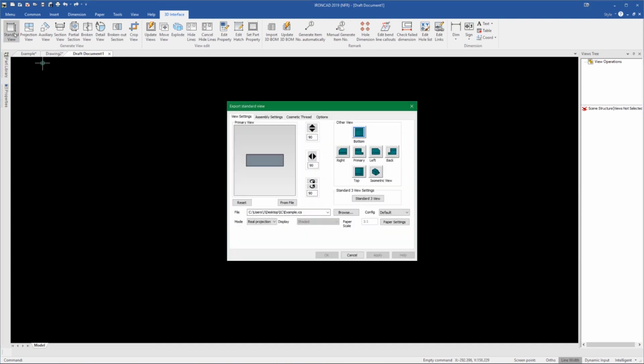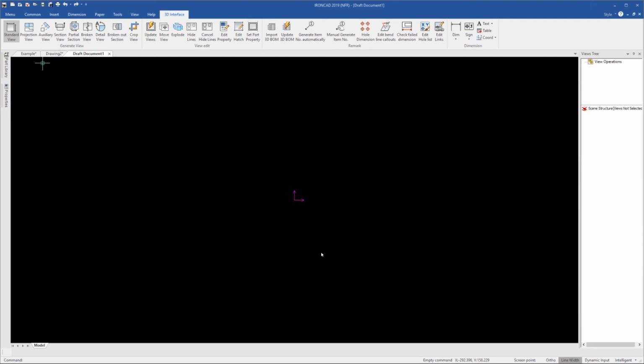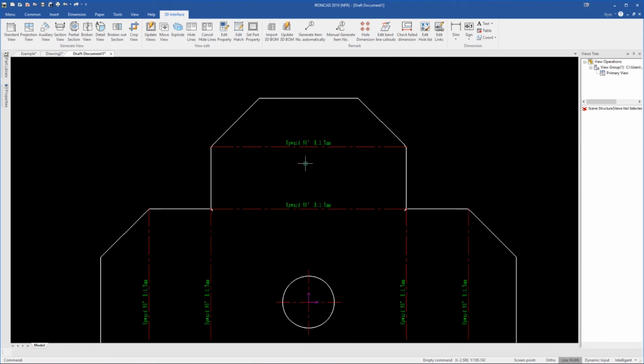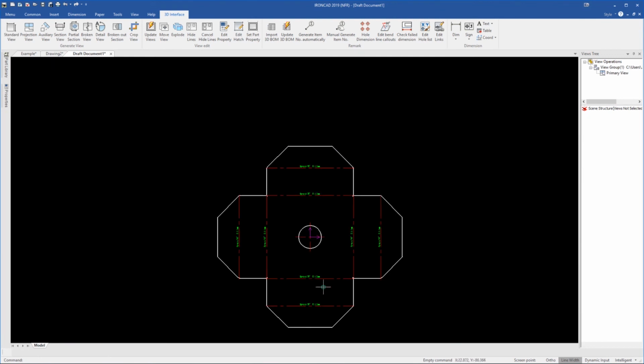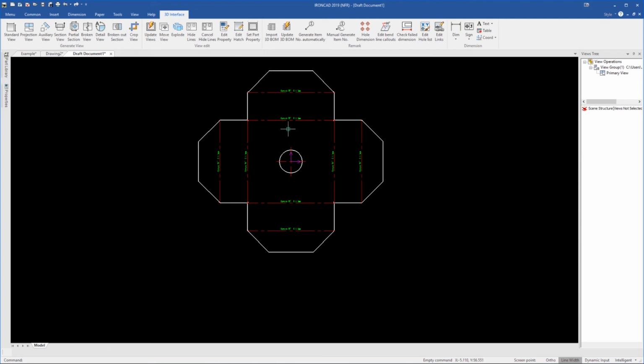For example, here in this case, if we just wanted a quick one-to-one DXF, we could go in here and do the unfolded view, and we'll choose the top view, or we can flip it here and then choose the primary view. Then in options, we'll bring in our bend line annotations, and then click OK. Click to place our view, and it'll bring in those bend dimensions and bend lines as well, and they'll be on separate layers by default, so that we have those set up and we can just save as right now as many different DXF versions from many different years to send them ready to go for laser cutting and so on and so forth.